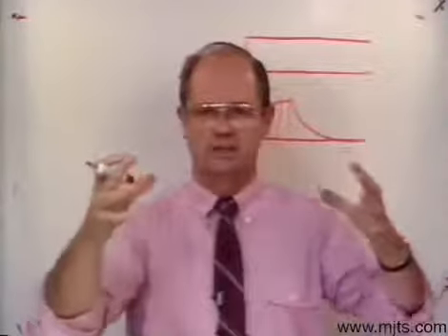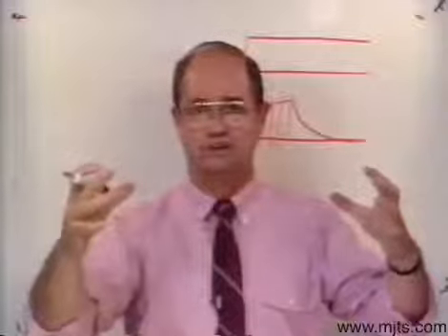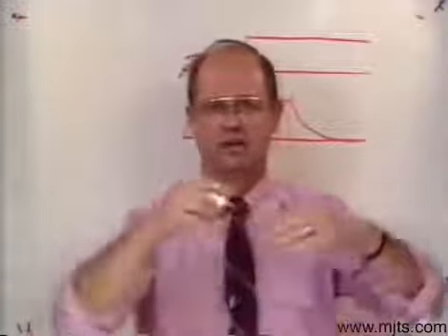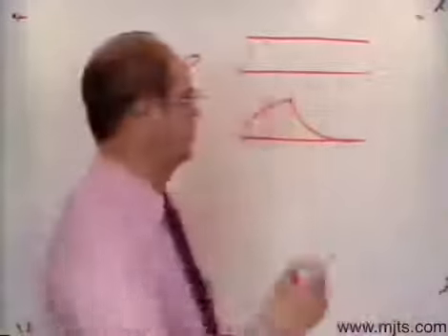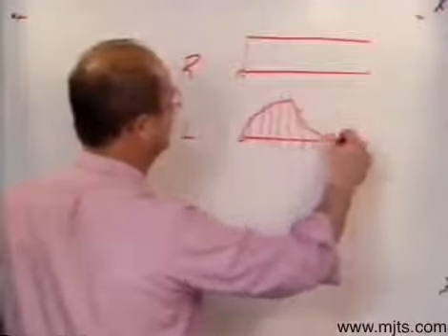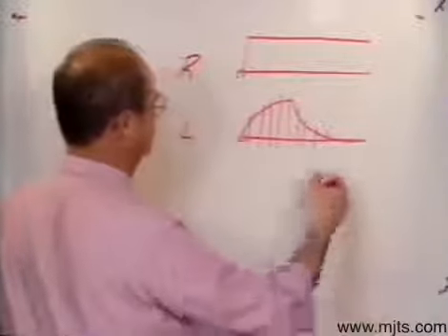And of course, because you have a situation where it's opposing a change in the current flow, it's trying to go to 0, but it can't go down there instantaneously because of the counter electromotive force again built back on itself. Now what it'll do, it'll go through 5 time constants again, all the way until it gets down to 0 again.